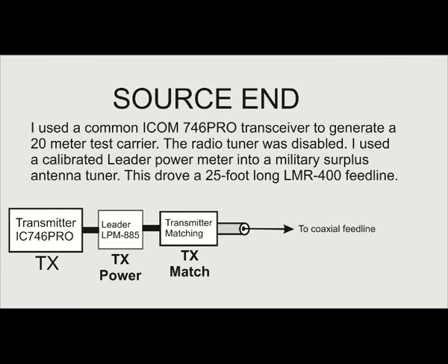This loss of power that shows up in these tables actually is at the source end. It's because the source is mismatched to the impedance presented by the cable, and the source simply can't deliver the rated power or the expected power into the transmission line because the transmission line no longer looks like what the source wants as a termination.